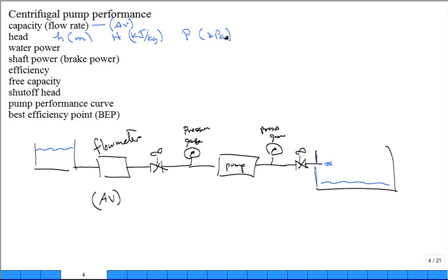So I may have a pressure gauge right here, but that pressure gauge may tell me meters of water column. Maybe somebody says, I want a really long manometer there. Great, put a long manometer there, and that'll actually show you the meters. But you may need something that goes over 100 meters, so that's ridiculous, right, for a manometer.